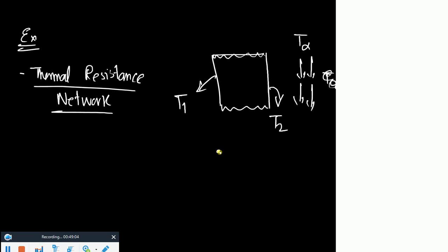Look at this side. Just like your electrical circuit course, on this side, instead of voltage, you have temperature. Then you have this wall, and this wall needs to be represented as what kind of thermal resistance? Conductive resistance. Okay. So I represent it like this, and I say that this is R conduction. You understand that?